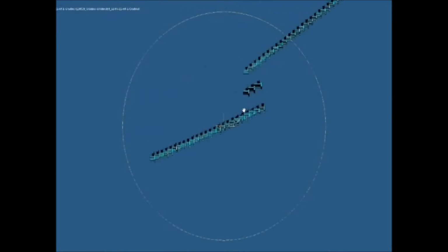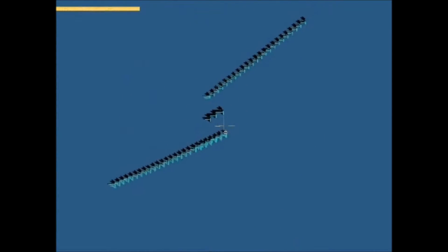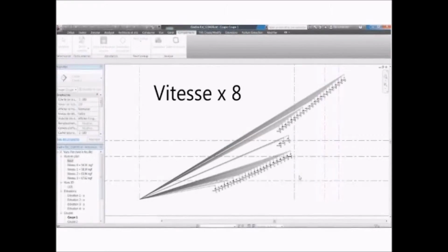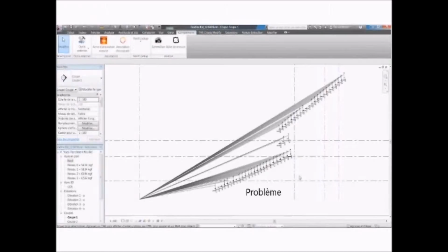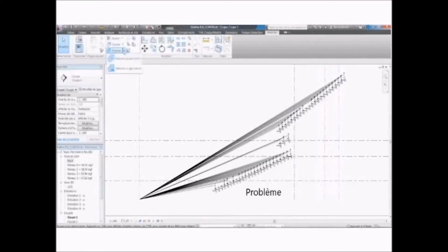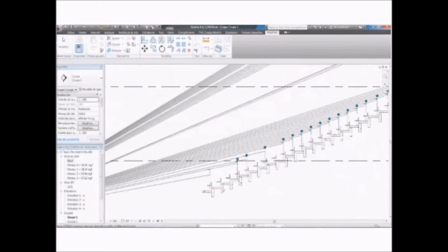After this reconsolidation, we chose to design the seats and the precast tiers as a whole because we realized, when analyzing the architect cross-section, that the prefabricated beams required millimeter accuracy, which was not compatible with the precast material. We did two things: redesign the tiered seating to ensure a proper visibility curve, and optimize the fabricated beams with the centimeter accuracy.